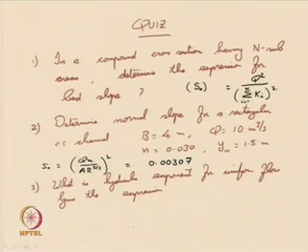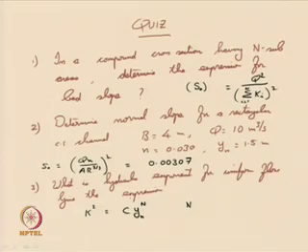So, what is the hydraulic exponent for uniform flow? You recall the expression for conveyance factor: K squared is equal to some coefficient C times the normal depth raised to an exponent capital N. This capital N is called the hydraulic exponent for uniform flow.